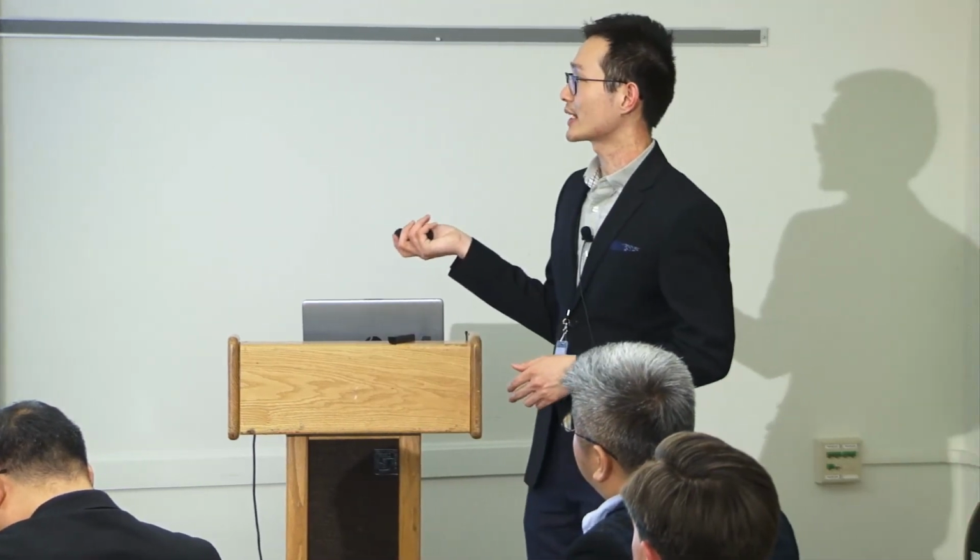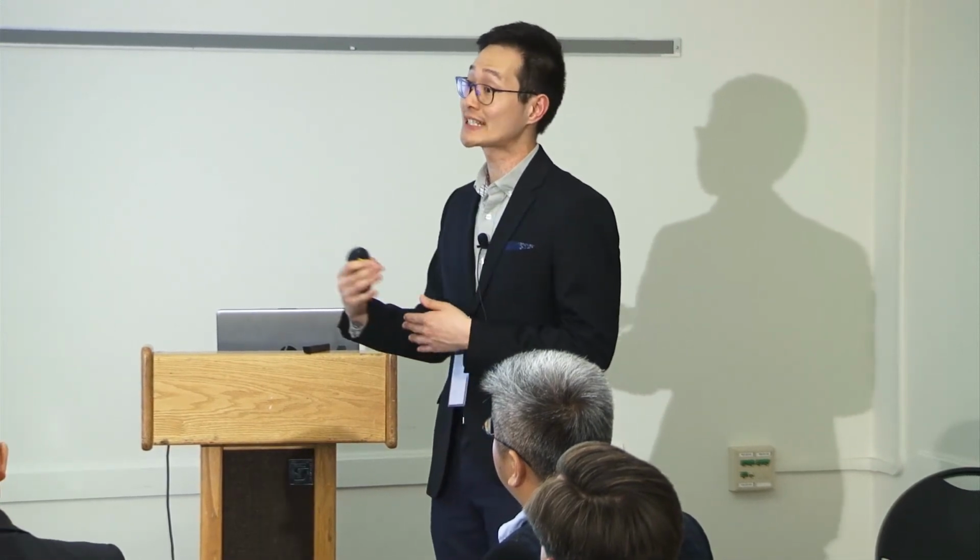Yes, that's right. I didn't show that the reactor performance is very sensitive to the operating temperature. So in our analysis, we assume it's isothermal. But there are a lot of engineering ways to integrate this reactor into solar. For example, shining the concentrated solar power directly onto this membrane reactor, or heating up the inlet gases. So in that case, it might not be isothermal.